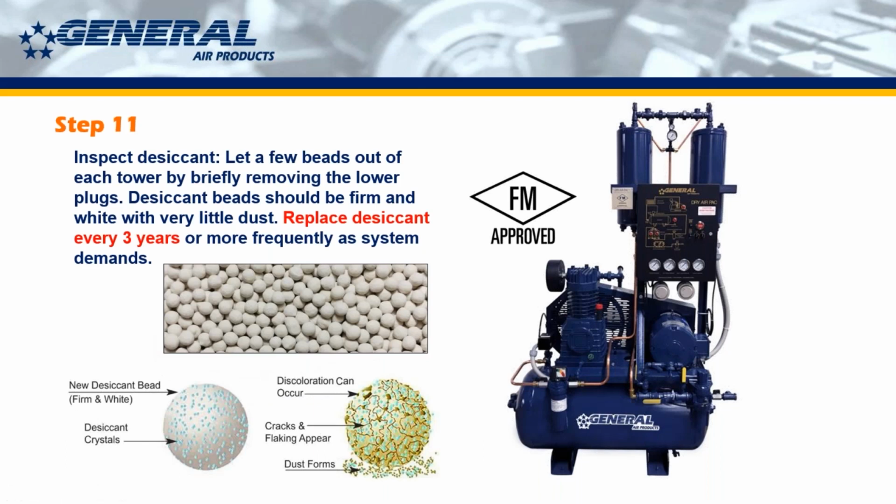Inspect the desiccant. So again, it should be bright white, very solid. If it's even a little bit off color, like yellowish or grayish, and also if it's soft and it breaks apart in your hand, it's certainly time to replace it.